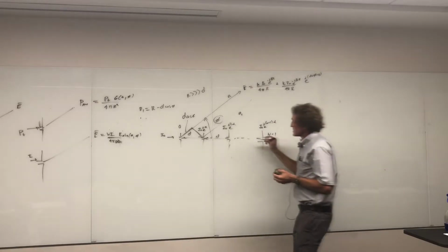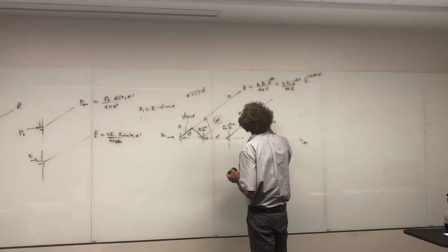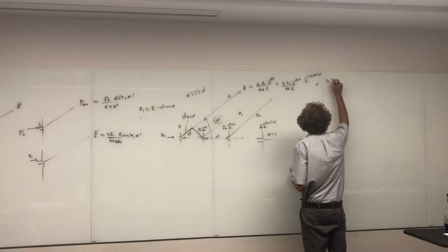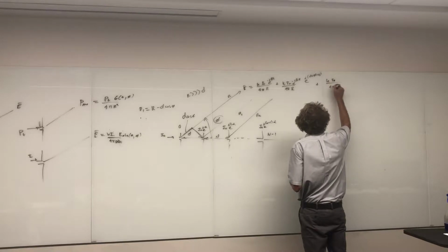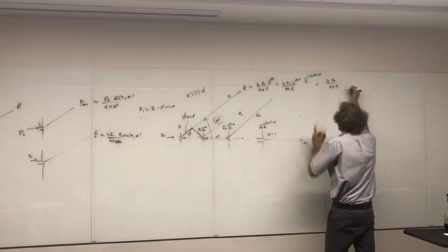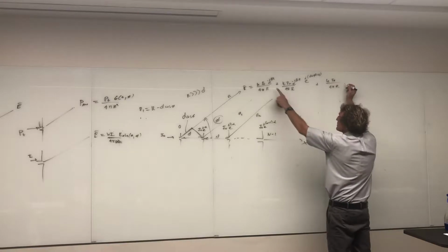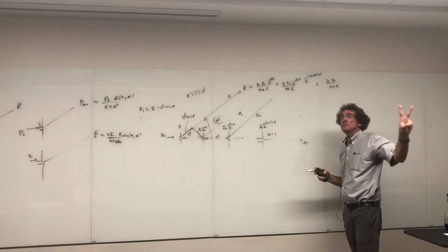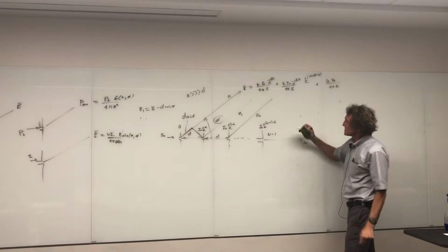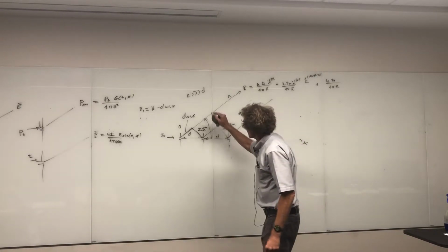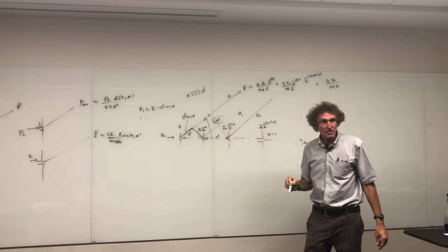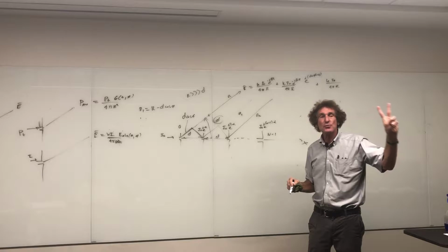Now what do you think happens here to the third one? Now that R2. Normally I'd have what? Plus k I naught, right, over 4 pi r, right? Then I would get what? E to the minus j beta quantity r minus 2d cosine phi, right? Because now, look, the distance difference is going to be twice the first one. Do you all see that, class? And the phase change is 2 alpha, right?